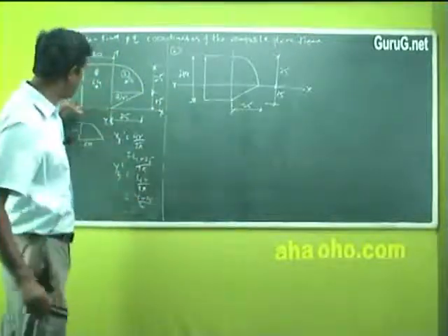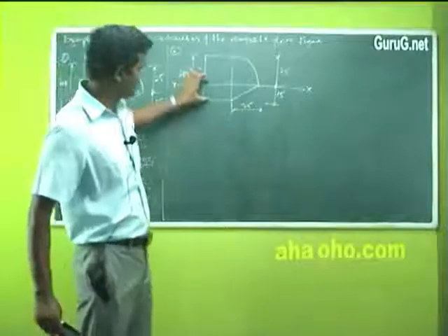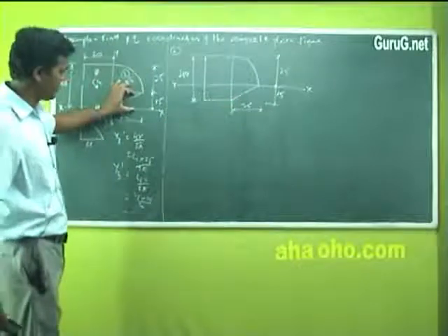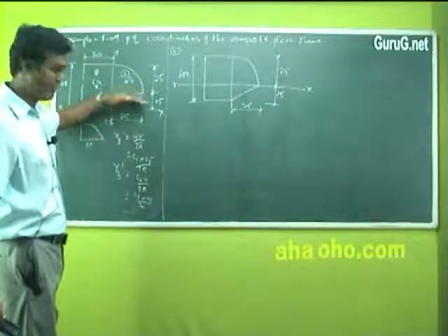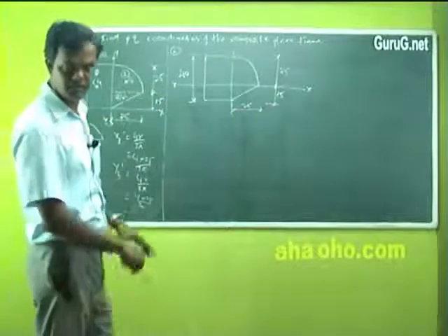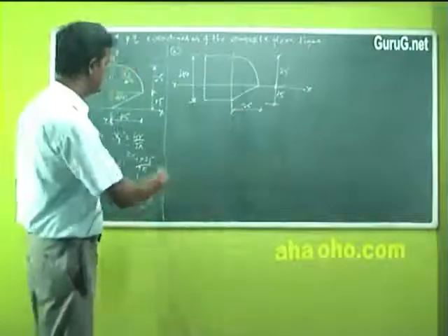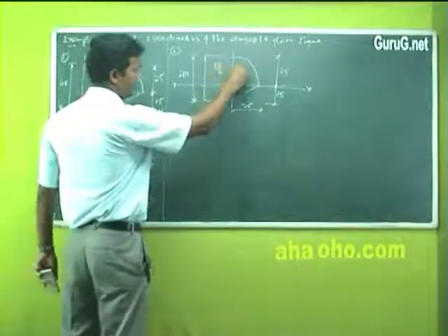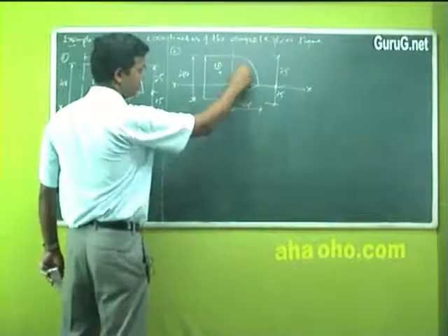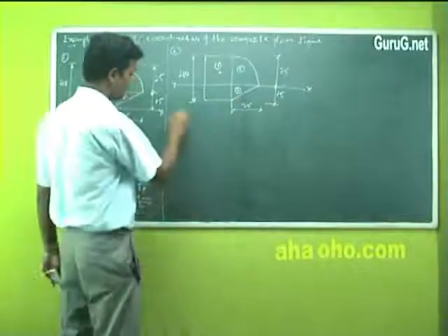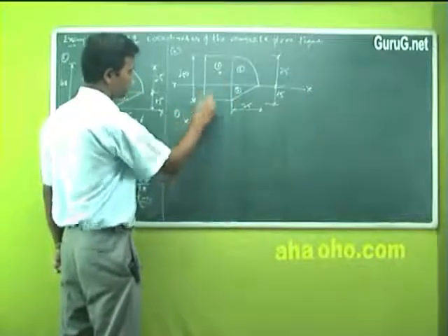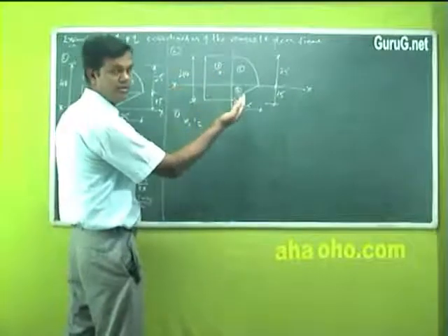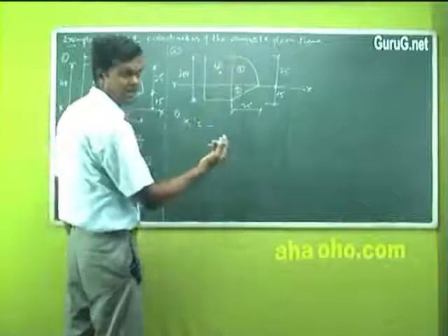Now one more sketch I have drawn here just to differentiate from the same sketch. I have just shifted this x axis to a distance at center 15 here. See, it starts from 15, the total rectangle here. Just one shift of the x axis. What will happen here? For sketch number 1 this is the rectangle, 2 is the triangle, 3 is the quadrant. For 1 you write x1 dash. How do you write this one? X is again traveling towards left or right? Left of this, so obviously negative.